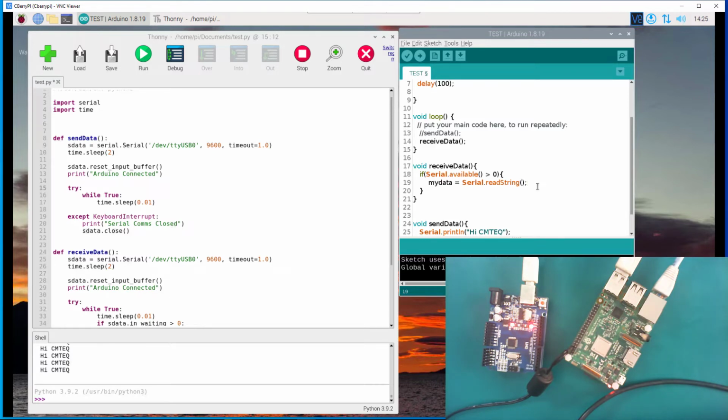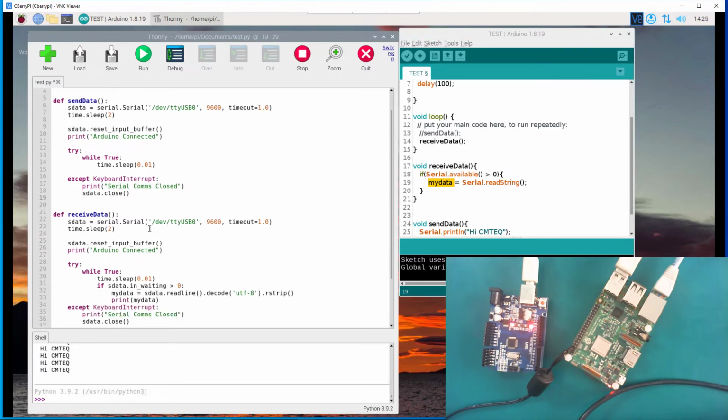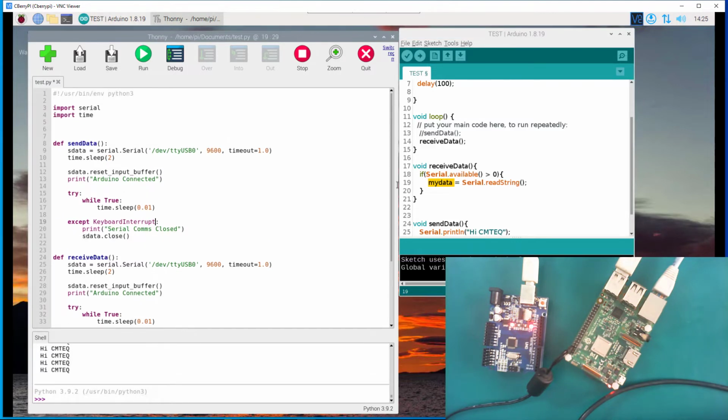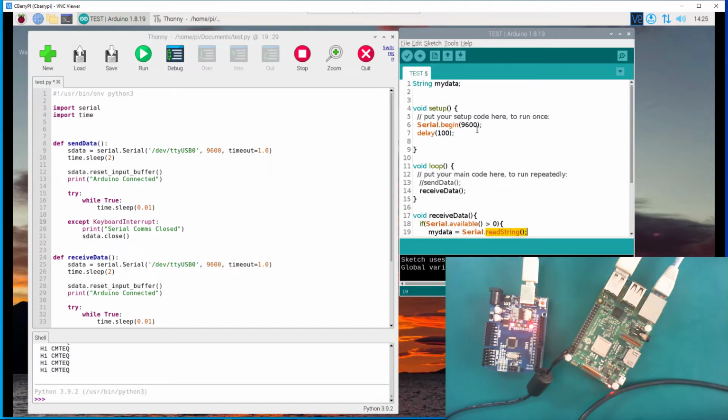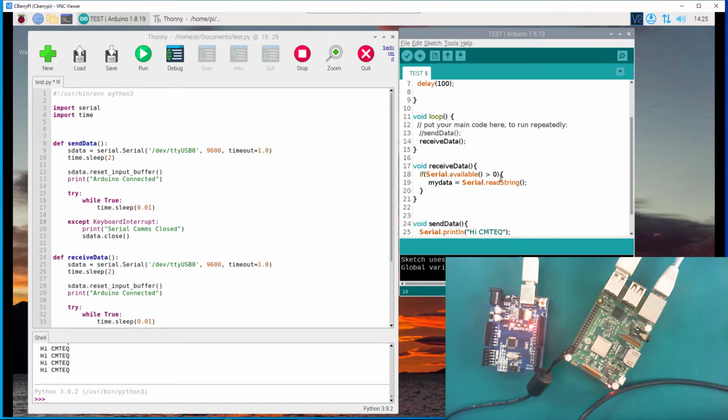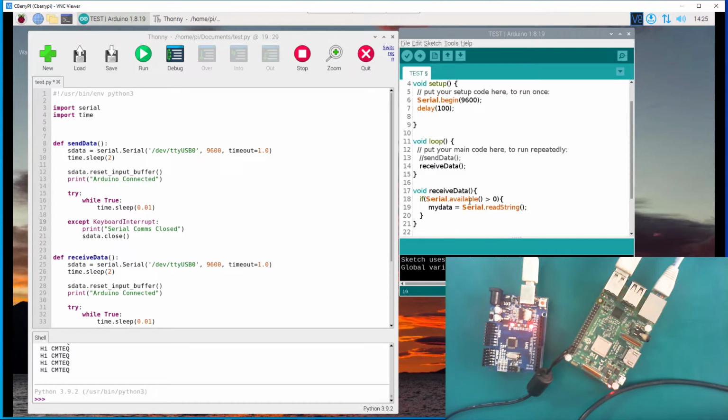So it will be waiting for 1 second before it actually assigns the data into your variable, to check if there is no other data coming. One option, if you want to stick with readString, is to force the timeout from 1 second to maybe a couple of milliseconds.